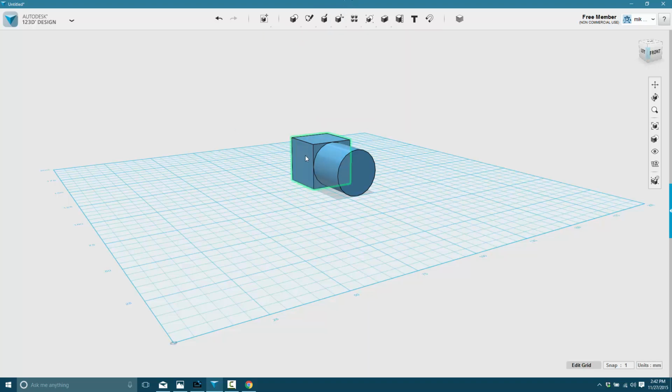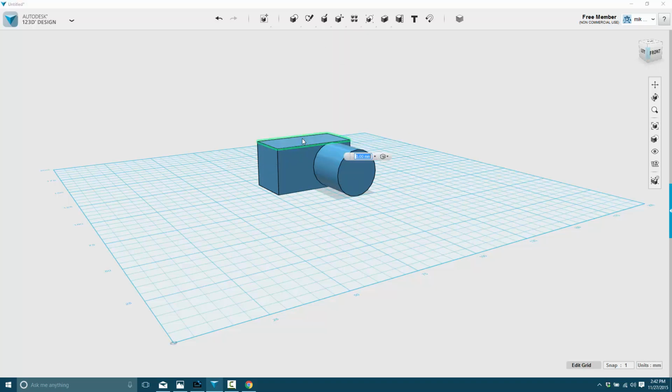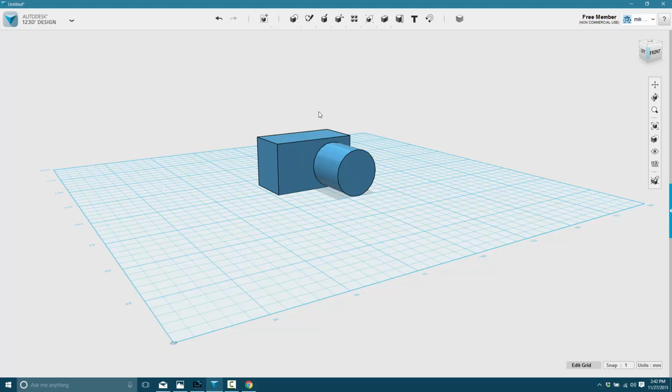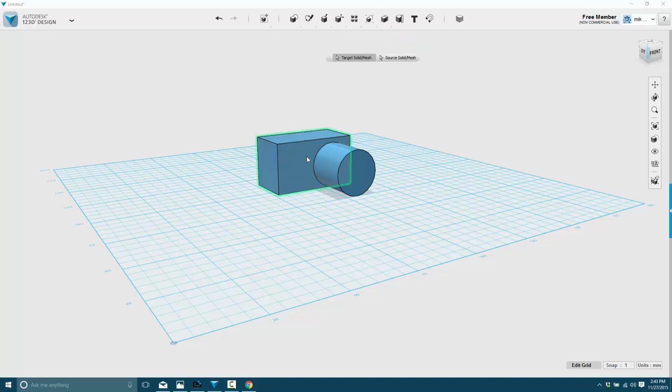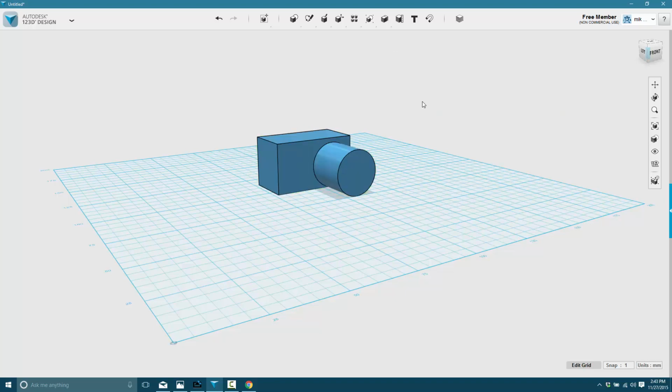Let's grab this guy and pull this edge out a bit. It's called an extrude, but if you're from the 3D world, it's not what you think because it didn't leave the old edges or faces behind. So you gotta stop thinking in polygons. You don't work in polygons anymore. We probably also want the surface to be slightly higher, so same tool, like so. Bring that up. Now we got the basis of a camera going on here. Let's just go ahead and combine those two together. So that's a merge. Pick surface 1, pick surface 2, and press enter. And boom, we have the basis of a camera.